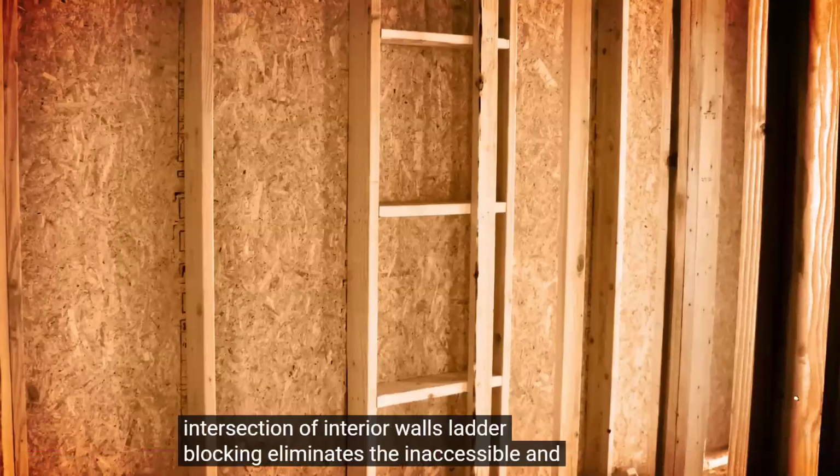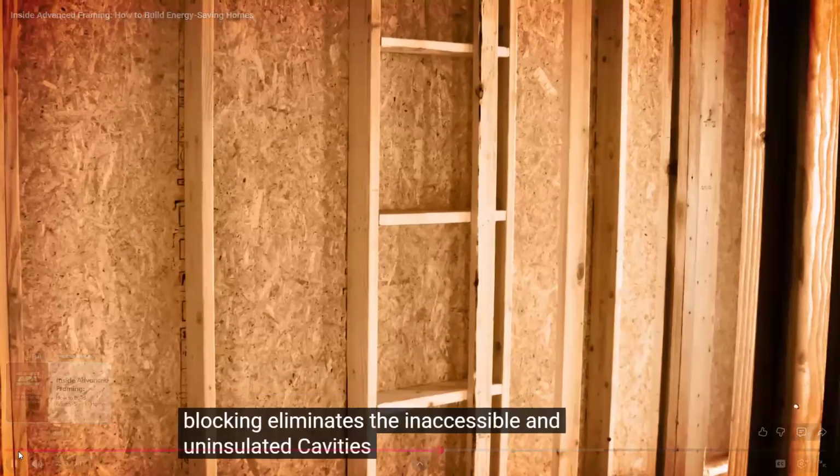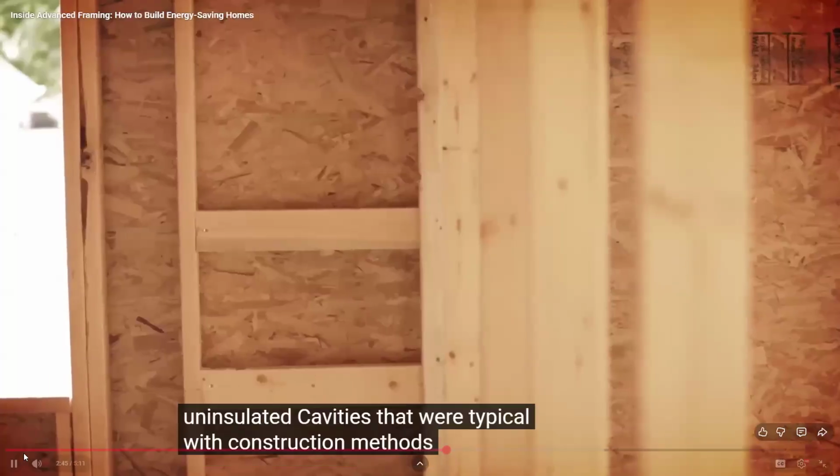Because like this horizontal piece here is a thermal bridge through your insulation, and there's really no reason why you can't put them vertically and still have a nailing surface. So I'm going to show you that. Keep an eye on the next one they show you. Uninsulated cavities that were typical with construction methods of the past.